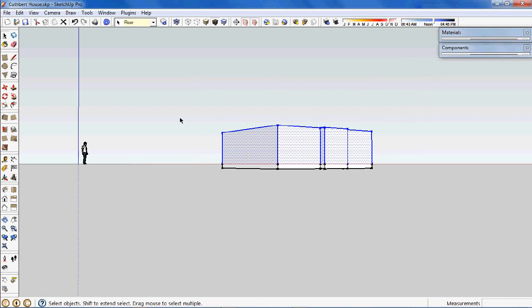And as I said before, all of those entities are on the floor layer, but I'd like to drop down the layer drop down box and change those to be the wall layer. Okay, so all of those entities are now on the layer called wall.